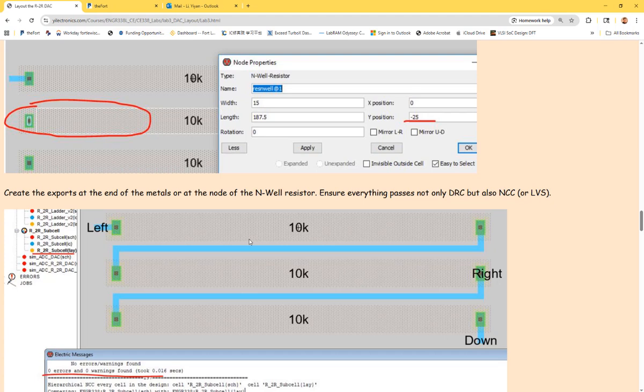And what that layer is, remember from yesterday? It should be metal 1, right? So you got a metal 1 over here, but it's still deep inside the chip. Eventually, you have all these layers from bottom up, and eventually you have metal 3 on the top. On top of metal 3, there's another silicon dioxide layer, which is the passivation layer. The thing is, there's a certain library component in Electric VLSI that allows you to have a little opening on the top of metal 3.